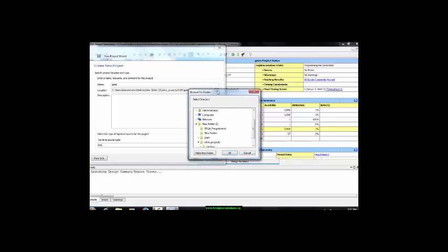and we will change our location. Let it be on the desktop. We'll make a new folder here. The name may be Brainiac. Double click. Okay, we can make a new folder within it. Let it be VHDL for proper management of our designs. Press OK.